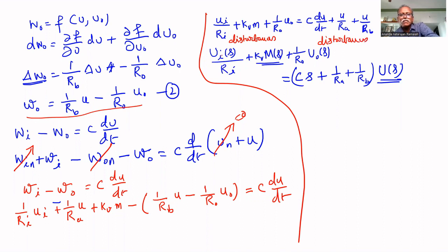If upstream pressure increases, flow rate will increase. Upstream pressure decreases, flow rate will decrease. Downstream pressure increases, flow rate will decrease. Downstream pressure decreases, flow rate will increase. And if you manipulate M, flow rate will increase and pressure will increase.